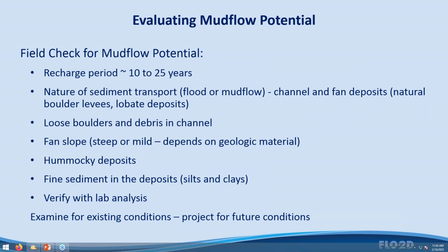for several, unless you have several smaller events in the intermediate period. And what you should do in that case then is identify for the client or for the agency how long you expect it to occur before the next event might generate a mud flow event, and that they're going to get flooding on any future rainfall events, and that they should make periodic inspections, especially after a small, say a seasonal rainstorm or several small rainstorms in the watershed, and get up and take a look and see how much material has been stored in the channel.